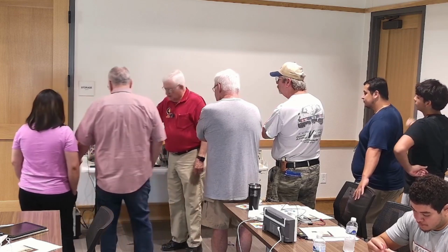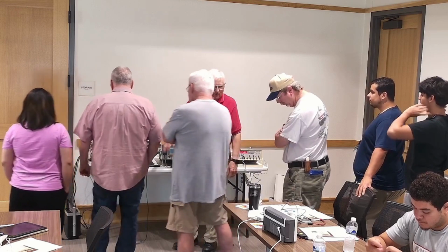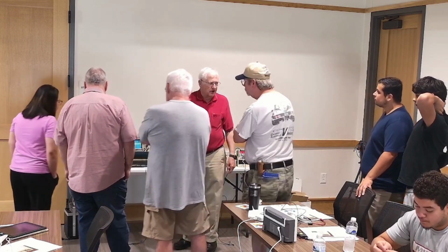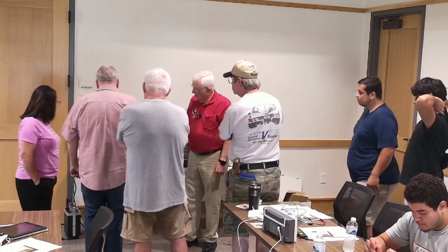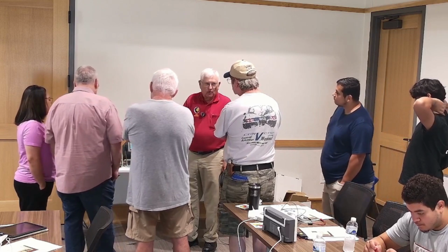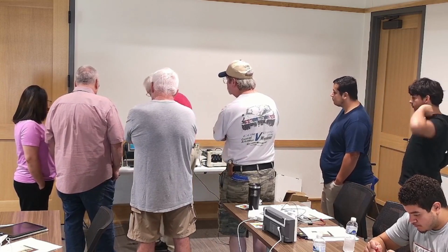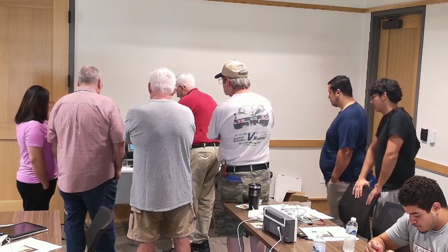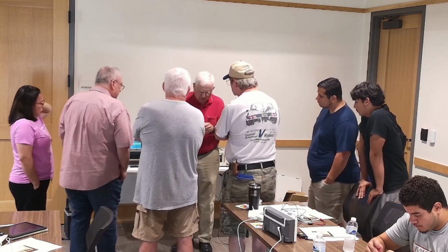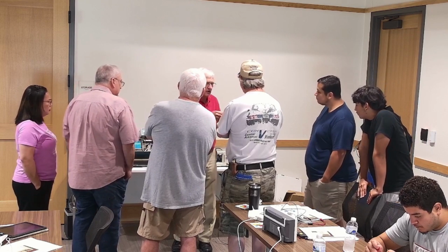What you're seeing on it is its internal generator. Most scopes have an internal generator. It gives you usually a 1 kilohertz signal at about 1 volt or so, and that's basically used for 2 things: one, to see if it's working, and the second thing, if you notice on these probes, let me just take this one off of here.